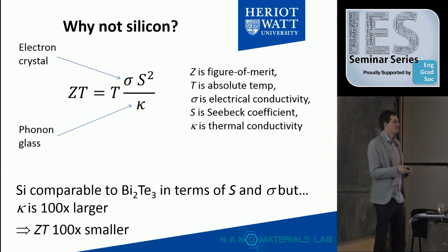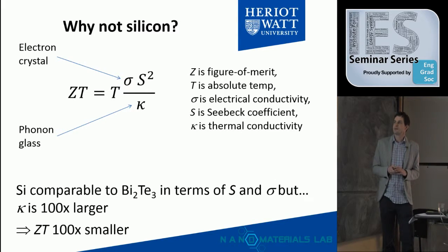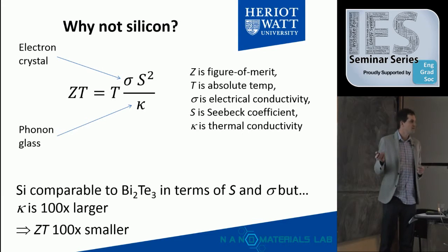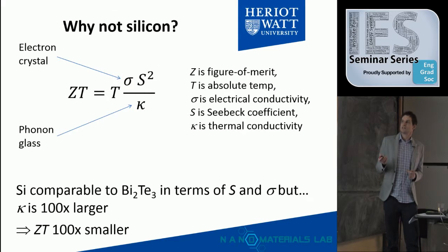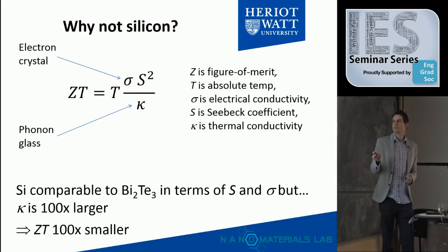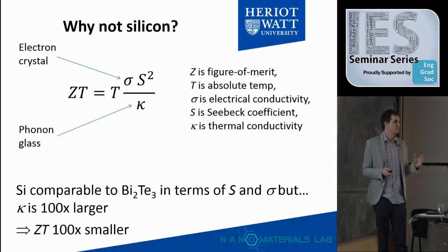But the big issue is that it's a pretty rubbish thermoelectric material, so that's a pretty compelling reason not to use it for thermoelectrics. And we know that because we can look back at this ZT that I've mentioned already. Just to say a little more, the ZT, the Z is the figure of merit. It's usually described in this way, multiplied by T, because that makes it unitless, so we can just give a number in order to compare materials.